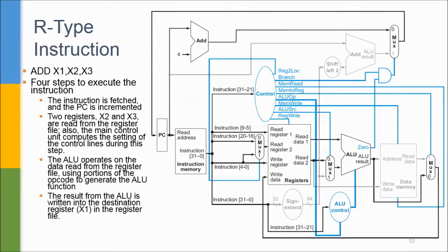The asserted control signals and active data path elements are highlighted in each of these slides. A multiplexer whose control is 0 has a definite action even if its control line is not highlighted. Multiple-bit control signals are highlighted if any constituent signal is asserted.